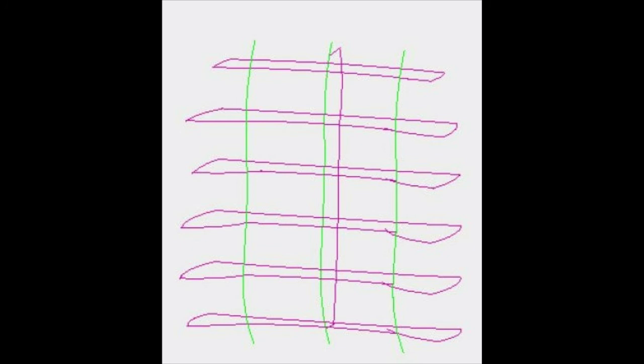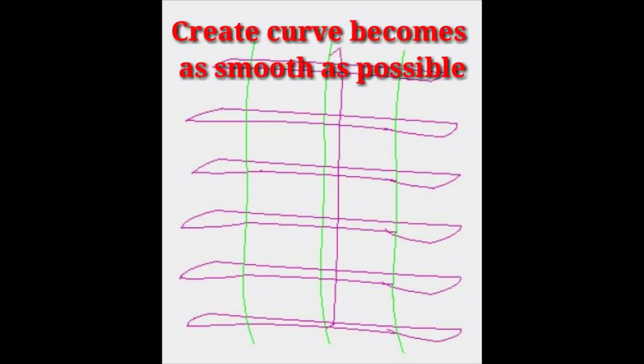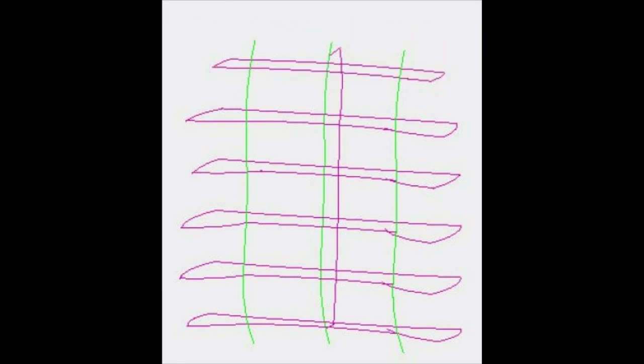This will allow the designer to create the curve on a plane rather than using the projection curve, as was done when the bolster and the side surface driving curves were created. Again, it is absolutely critical that the surfaces are created as smooth as possible and not deviating too far from the design intent. You can see the image.